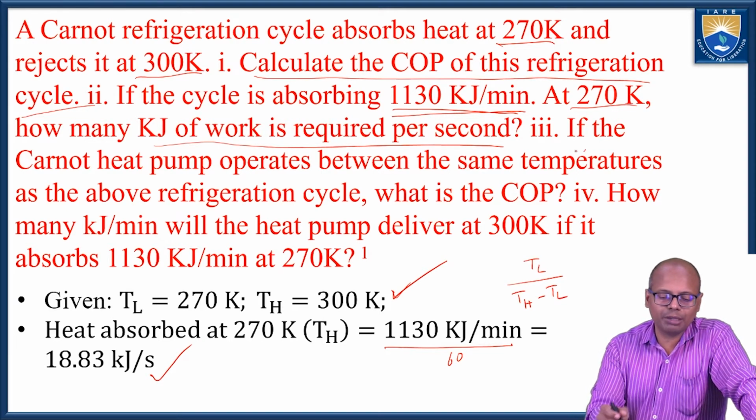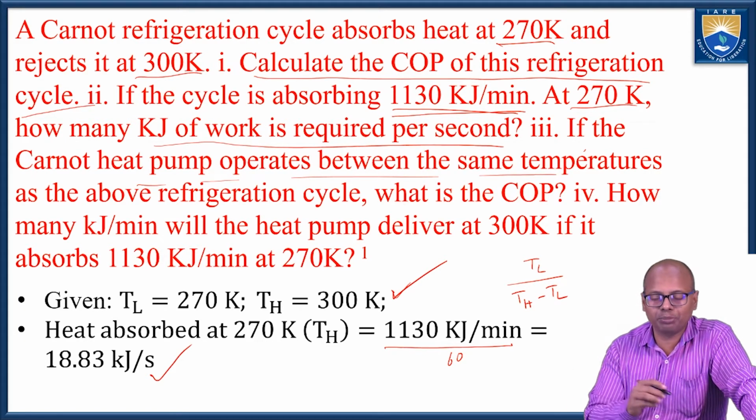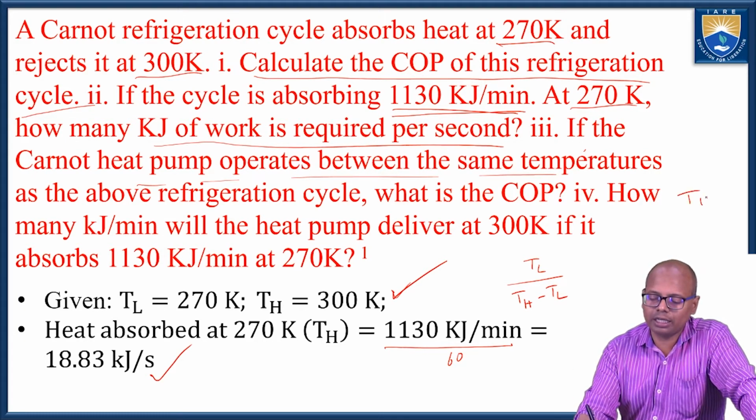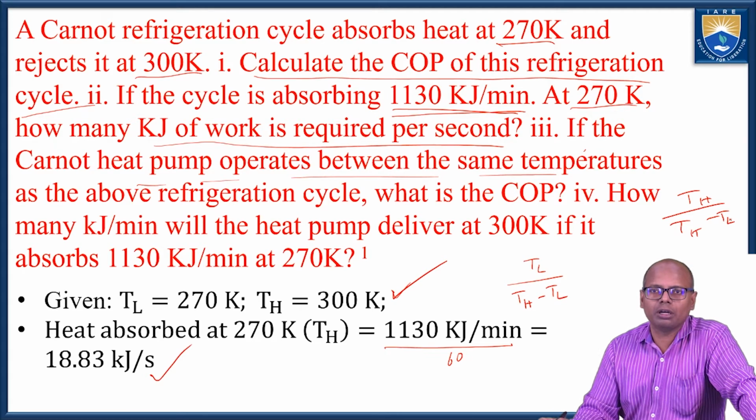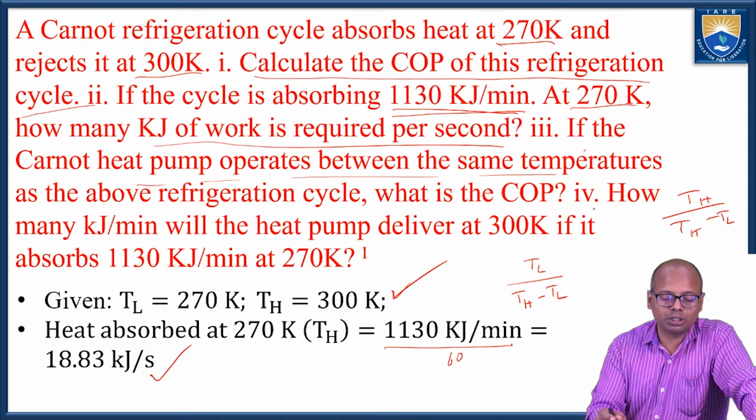Now, if the same thing operates as a Carnot heat pump, what is the COP? If it is a heat pump, again, it is the higher temperature divided by TH minus TL. So this is the COP for the heat pump. Now, what is the fourth bit?